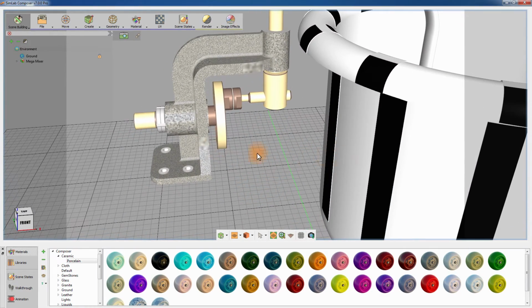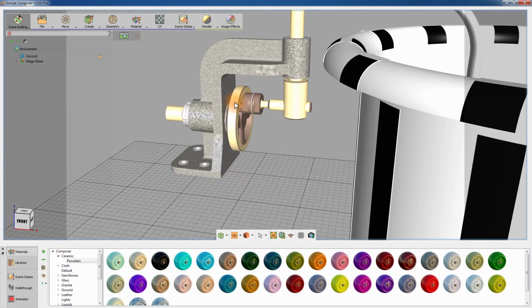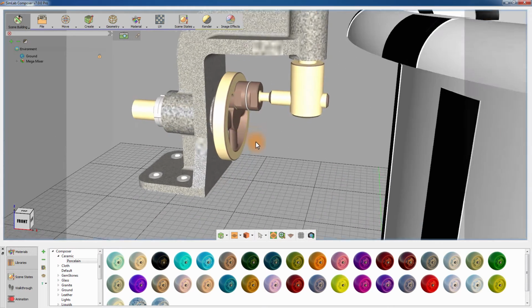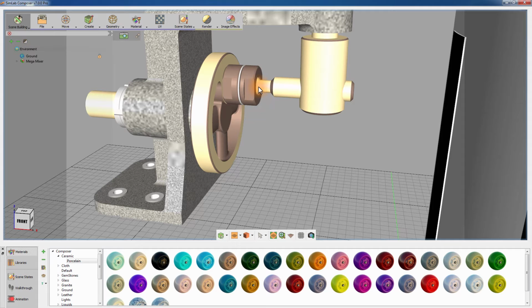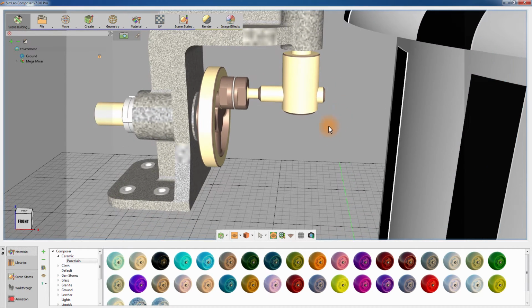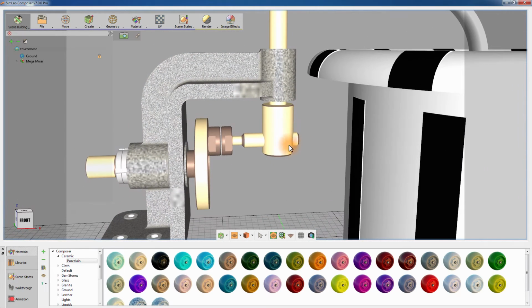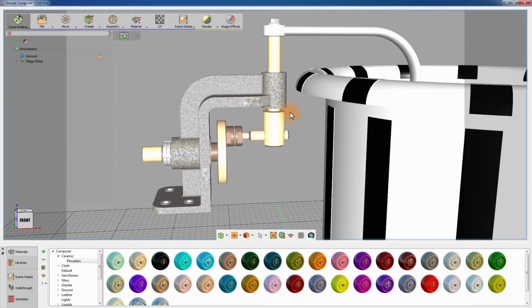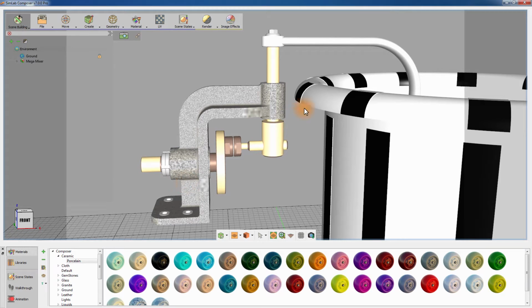This horizontal rod is driven by a motor, which will make it rotate around its axis since it is held by the fixed metal arm. This gear is connected to the motor rod and will rotate along with it. The pin has a ball joint connecting it to the gear, which would give it the freedom to rotate in all directions, while the other side of the pin is connected to a vertical shaft through a cylindrical socket that is also stabilized by the fixed metal arm.